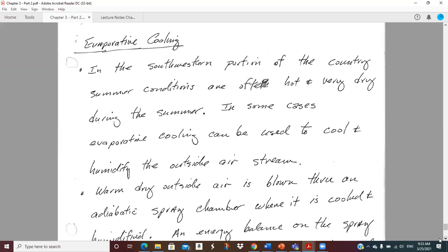Sometimes in kitchens, poor people that work in kitchens in the southeast in the summertime, sometimes the building owner or whoever owns the restaurant is too cheap to buy real air conditioning, and so they'll put in a swamp cooler. Well, you get a little bit of benefit, but of course you're throwing additional moisture in the space, and there's already a lot of moisture in a kitchen, so they don't really work very well.